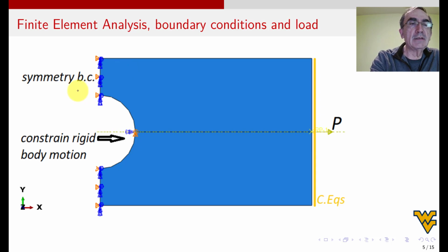So how this is done is that you impose a symmetry boundary condition with a feature that the software has, and it's easy enough. You just select this line here and this line here, and you click and you say symmetry with respect to this plane, and then it's done. Okay, that's easy. I could have modeled only a quarter by applying also symmetry along this line, but I decided to do the easy way to make it easy to explain.